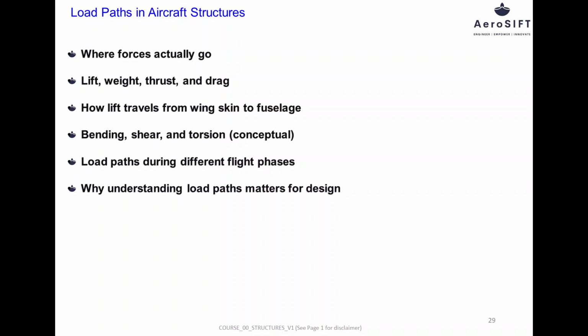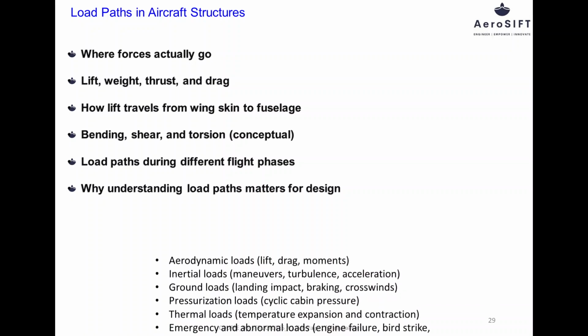Understanding load paths is fundamental to good aircraft structural design. Designers must ensure that every load has a clear, continuous, and efficient path through the structure, from where it is applied to where it is safely reacted. Poorly defined load paths lead to stress concentrations, unnecessary weight, and unpredictable behavior under real operating conditions. By designing with load paths in mind, engineers can place material only where it is needed, achieve redundancy and load sharing, and create structures that are both strong and damage tolerant.